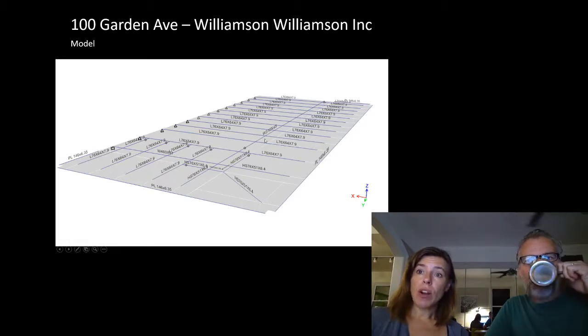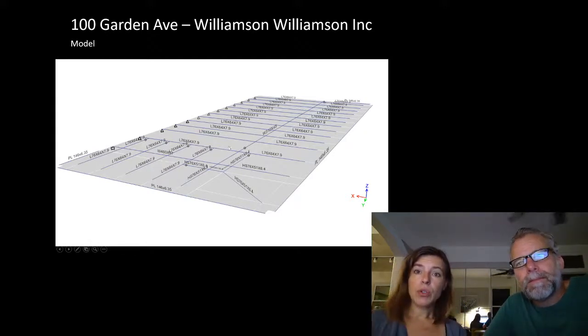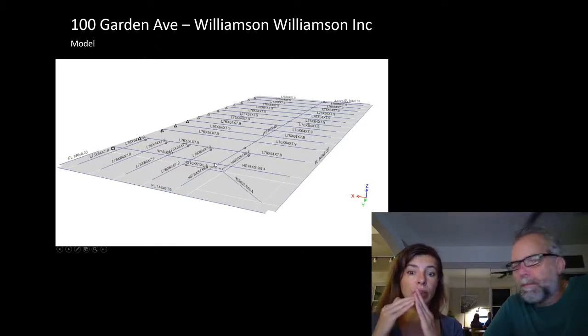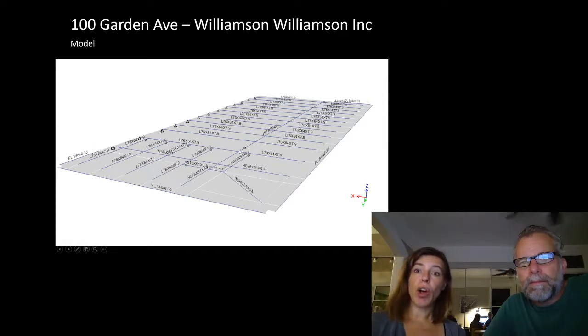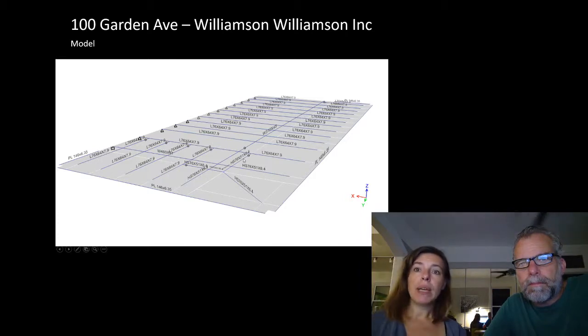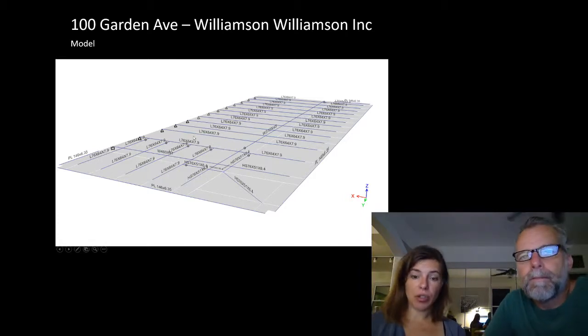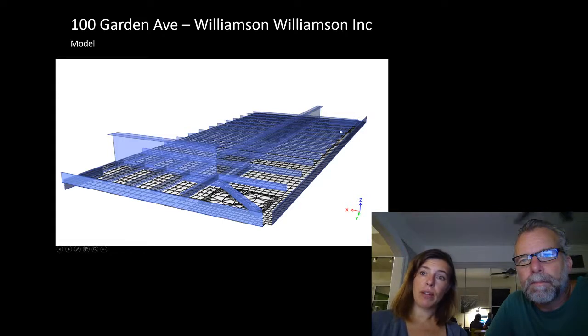So these big members are inside the envelope. Everything else is outside the envelope. So we didn't want a complicated moment connection at the intersection between inside environment and outside environment. So this pulled the complex connection out and kept it in our outside environment, meaning our interior connections could be kept quite simple. You can see these big members are the ones doing the framing for the second floor. And you can see my structural elements.